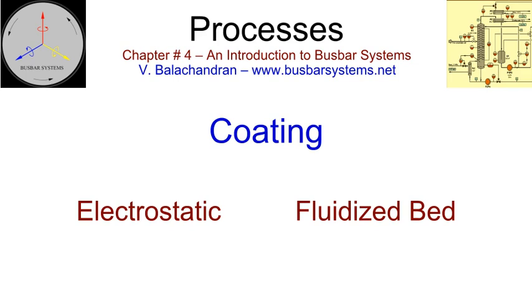The coating is carried out for flat bus bars normally used by most of the bus duct manufacturers. The conductors must have a smooth rounded edge to avoid any stress concentration. The coating material is a one-part epoxy system, which, at elevated temperature, bonds and sticks to the bus bar. Essentially, there are two methods of achieving a coat: electrostatic coat and fluidized bed coat.